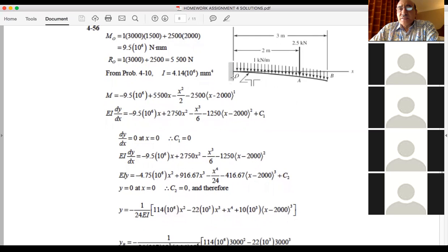And we start writing an equation for the moment distribution directly. So we're skipping, actually, usually we start from Q. We write it as an equation that has singularity functions. And then from Q, we find V by one single integration. And then we find M by another integration. And then once we find M, we're just going to move on to find the deflection by two more integrations.